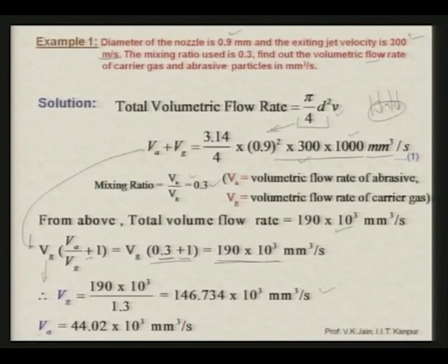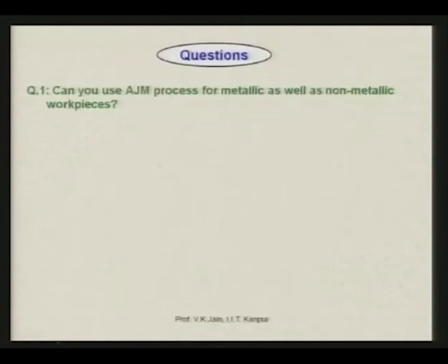Now, if we know the carrier gas flow rate, we can also calculate the abrasive flow rate, and that comes out to be 44.02 into 10 raised to power 3 cubic millimeter per second. So, in this way we can calculate the volumetric flow rate of abrasive particles as well as carrier gas.